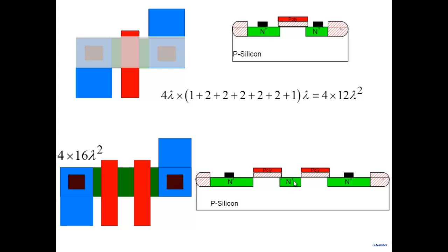And for example, if I call this the source and this is the drain, the drain and the source of the next 2 transistors are shared together. I mean, if this is the drain here and this is the drain of the second transistor, so the drain of the first transistor and the source of the second transistor are shared together. And note that this dimension is pretty small because I don't need to make a contact to it. When you have to make a contact to it, the dimensions become larger here.